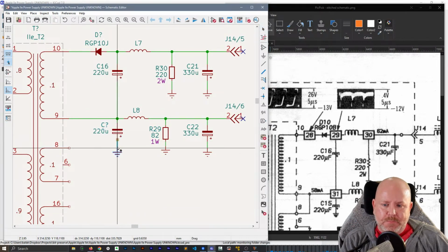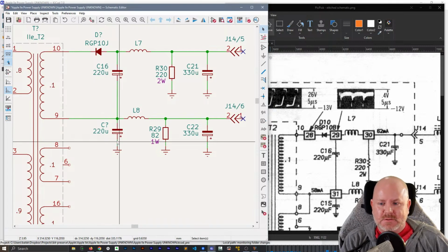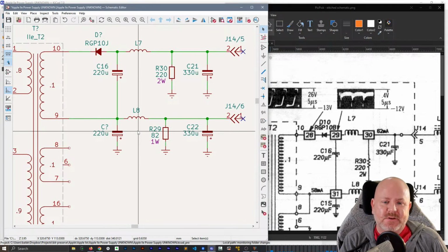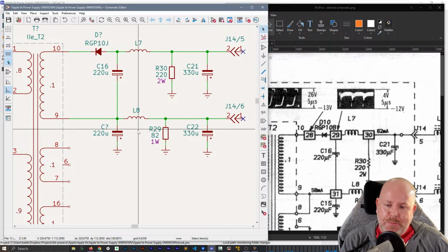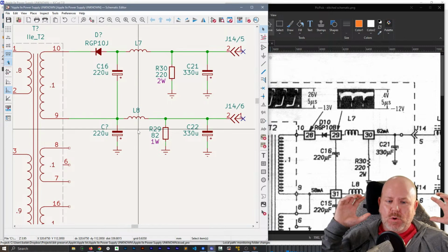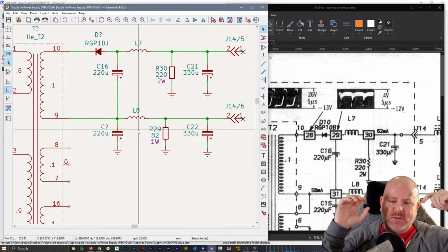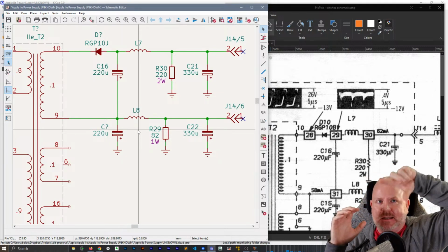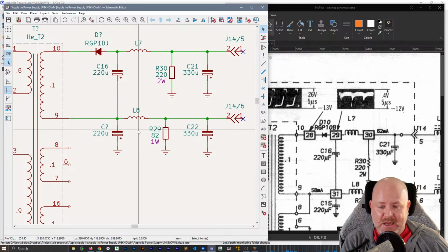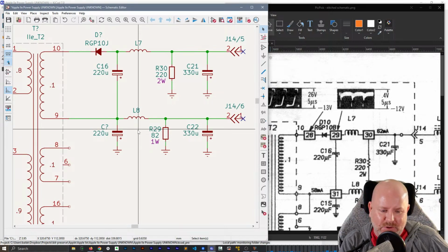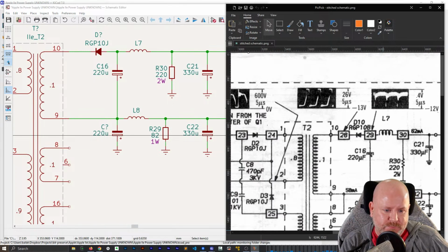But one of the things in the box of stuff was between 16 and 25 memory expansion boards for the Apple IIgs. I don't have any in here, but they basically allowed you to add up to 1 megabyte of memory into a IIgs. You would insert 8 DRAMs, and each bank of 8 DRAMs would increase the memory by 256K. So it's 256, 512, and 1 meg. 768 would actually cause problems because reasons.